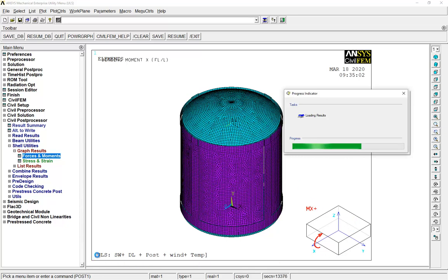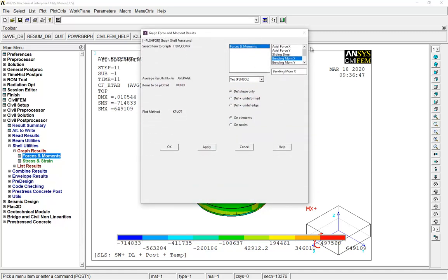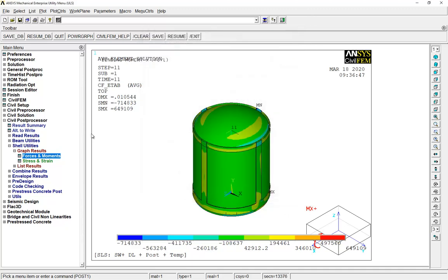Here you can see the ULS combination with the title self-weight plus test load plus tension forces plus wind plus temperature. I can add several combinations with the seismic loads and all this data. Here you can see the bending moment around the x-axis. Also, I could generate any of these axial forces, sliding shear, any of these forces. I can plot them, list these results, and also export.